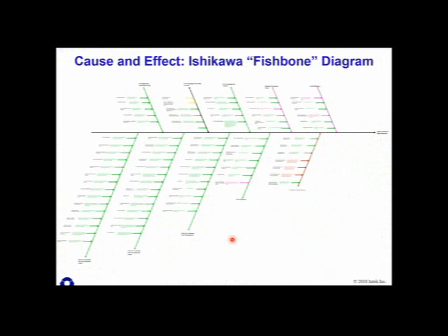You don't necessarily have to have this fishbone diagram, but it's a nice single document that can be passed on to new engineers, a consultant service, or even you can use it as a to-do checklist. You check off each one of these. I've checked all of these things to try and track down this high back pressure, but it's got the fundamentals of what you would need to do a complete assessment of the high condenser pressure. It's a nice single document that has the cause and effective detection activity. So I wanted to show that.